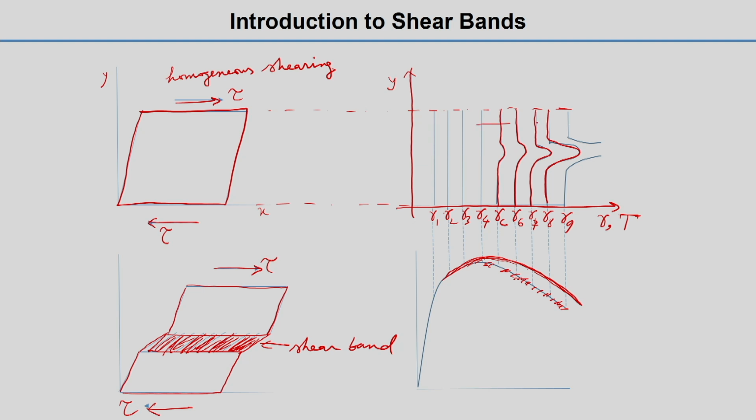So that means when we increase the tau in this direction, after a critical gamma, that means I would write critical shear strain, and before this area whatever strain we are talking about is homogeneous strain, and after that it was inhomogeneous because the shear band started forming.